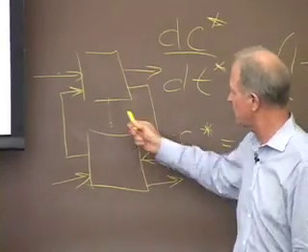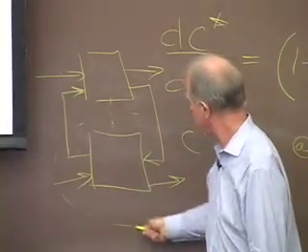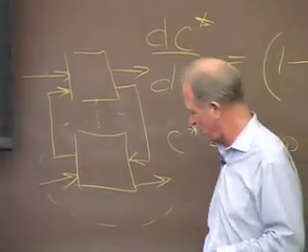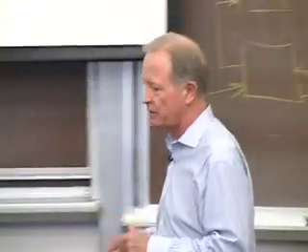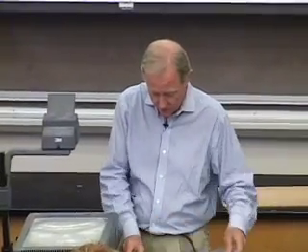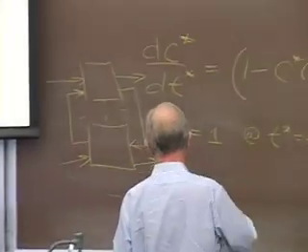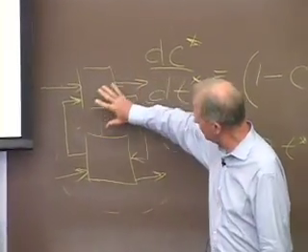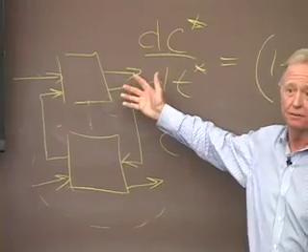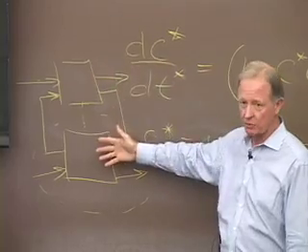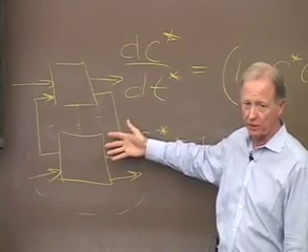You just make mass balances like you do around this unit, around that unit, and you'll start generating the differential equations that you need to solve in order to arrive at solutions that describe the dynamics of that kind of interesting tank system. I can connect lots of tanks together, and eventually this starts looking like a chemical plant. And now, instead of making steady state mass balances, you can make unsteady state mass balances.